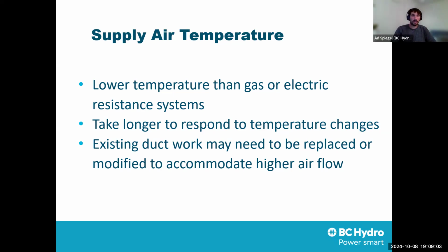But one of the bigger implications from a design standpoint around this low supply air temperature, especially when we're talking about central systems, is ductwork. The amount of energy delivered to a space is the temperature of the air times the quantity of air. How much air and how hot it is determines how much energy is delivered to that space. Well, we just said the temperature is now not as high as it was previously. So that means we need more airflow.